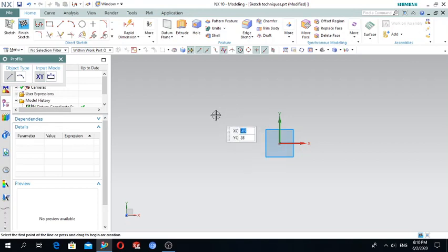To create a line, click in the graphic window with the left mouse, move the pointer and click again, move the pointer and click again. A line is created. After clicking for the second time, you can see that the end point is added and another line segment is created. It could be horizontal, vertical, or inclined. This is the convenient way to create a chain of lines.